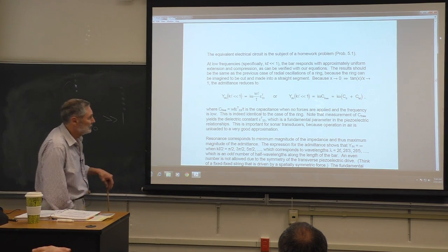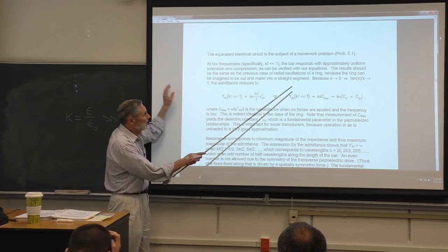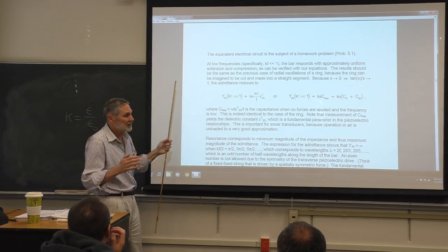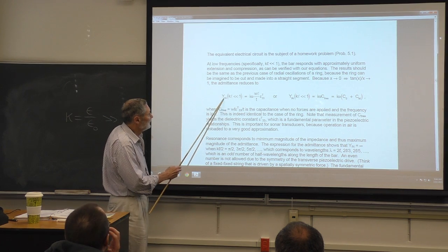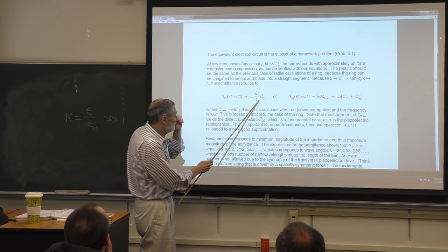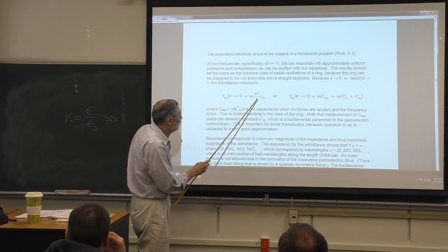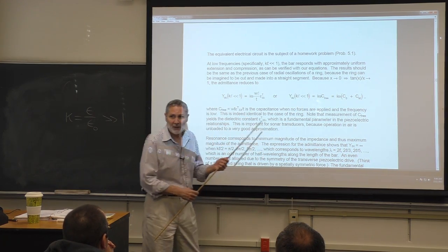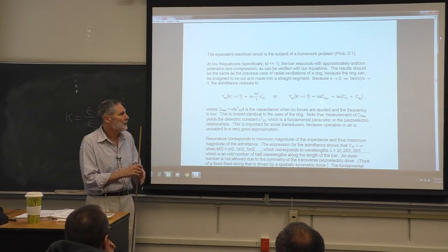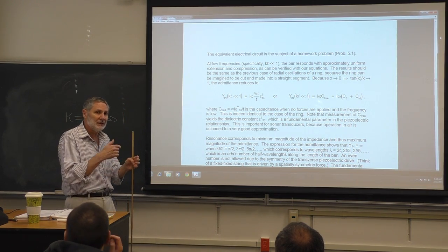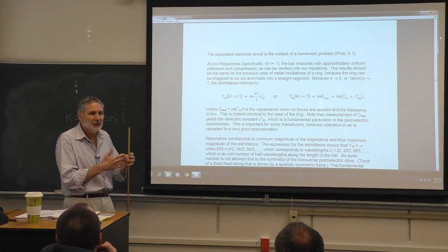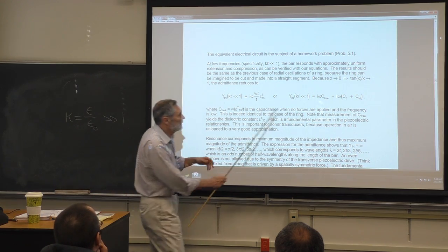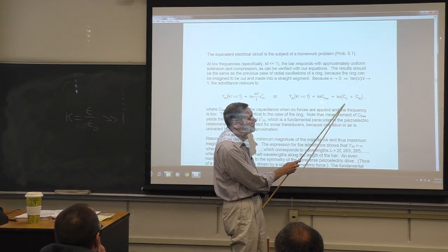That's easy to prove. When you take this quasi-static or low frequency limit, here's what we get for the input admittance. As you know from the lab, this is the free capacitance, because there's no load and it's mechanically moving. It involves the blocked capacitance and the motional capacitance. We call that the free capacitance. It's simply the sum of the two.